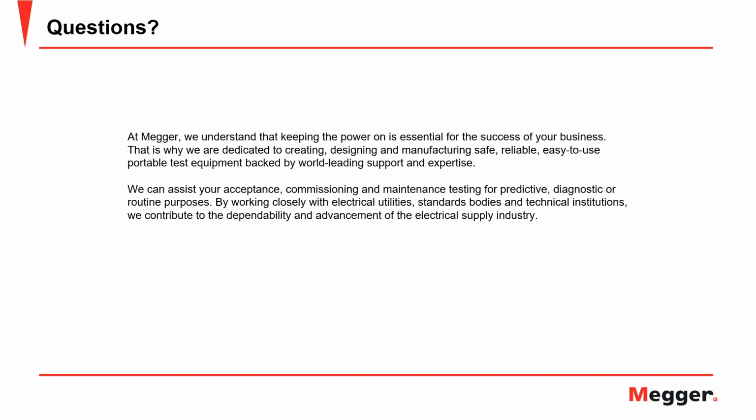I think it's the grounded specimen test that may differ when it's connected to the transformer itself or if it's standalone. So again, no, you don't need to remove it to test C1 or C2, but you may experience some slight measurement differences if you do measure it in the transformer installed and then separately.